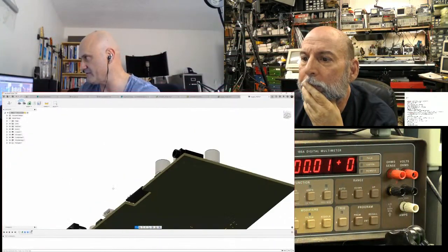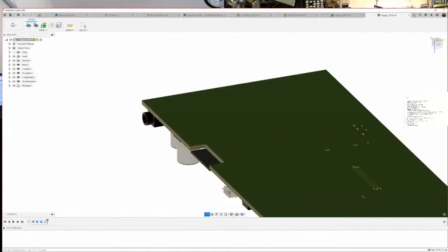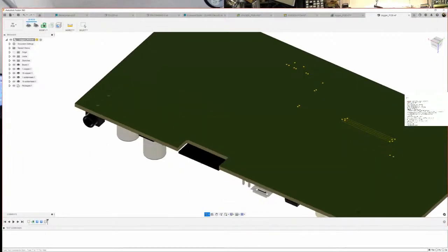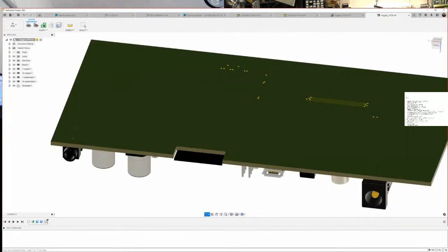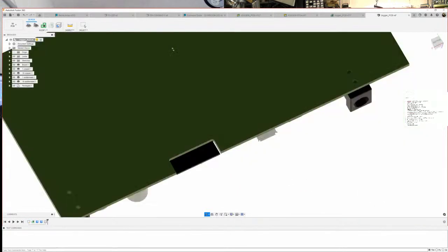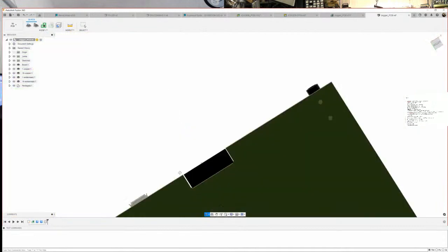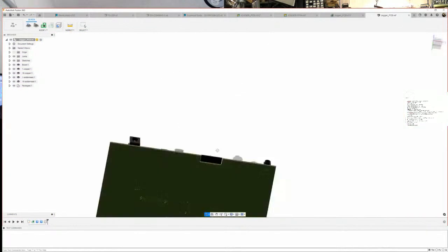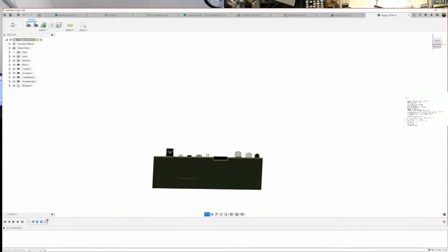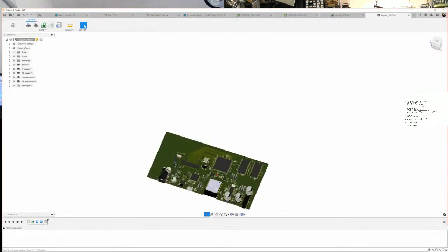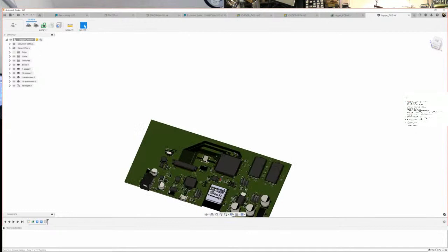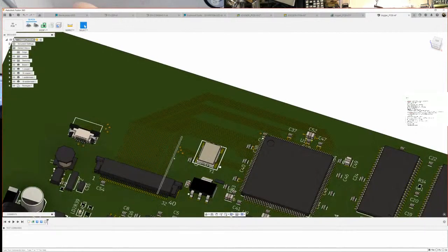See, I've left the back of the board completely blank because that's where the TFT is going to attach on the back side of the board, right? Right. So you did a technique there, though. None of your traces from the FPGA to that connector have to cross each other. So either you pinned out your connector to match the FPGA, or you pinned out your FPGA to match the connector, I'm thinking.